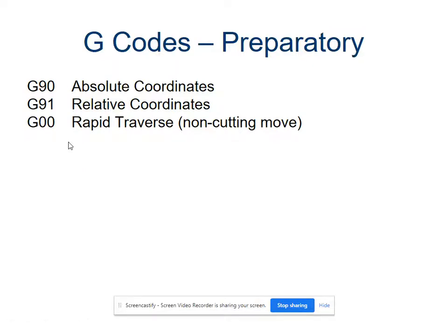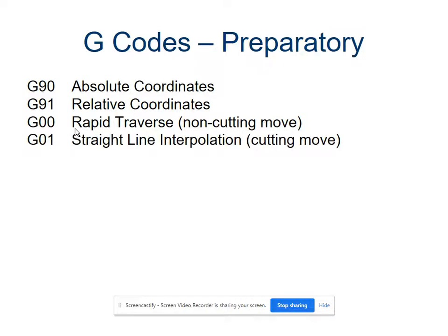You can set a feed rate for things, but the machine also has a programmed-in feed rate that you activate with G00, where it goes real fast across the table and stops at whatever the coordinate is that you put in. That is a non-cutting move. You never use G00 when you're cutting into something, because it will snap a tool bit or something else unfortunate.